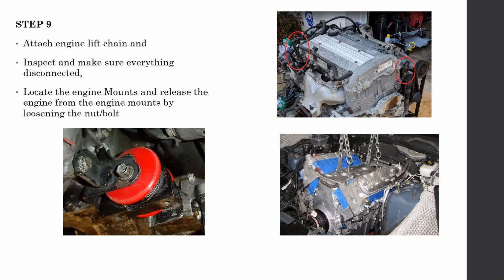These are places that generate higher vibration or collect vibration. If it is possible to put the mounts near such places, more vibration can be absorbed by the engine mount. So when designing engines, manufacturers try to put them as close as possible to these points, but unfortunately it is not 100% practical.